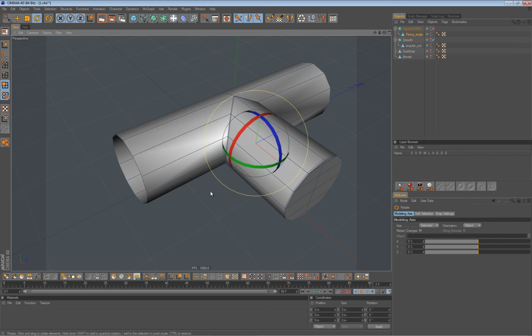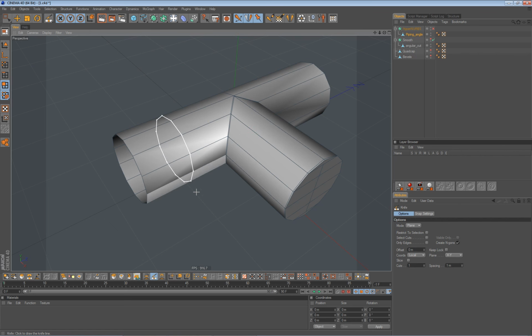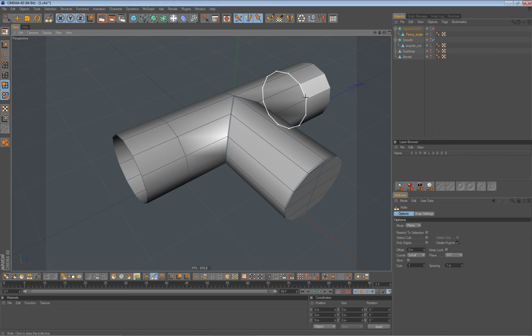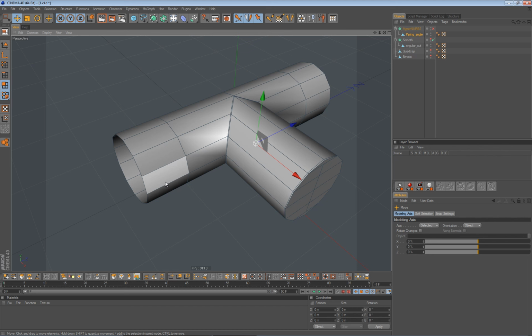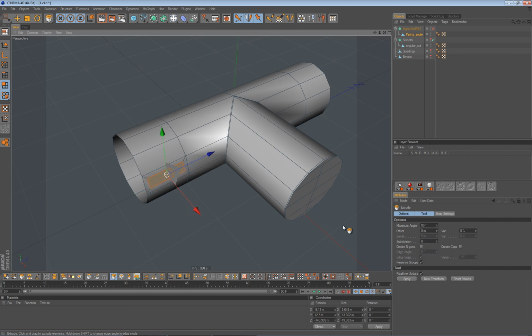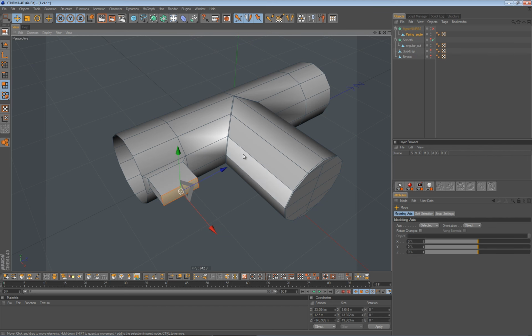Let's just do that. Let me select my knife tool, and it's in plane mode, because if I select loop mode, then this loop will be distorted because of this break in geometry. So I want nice clean loops. I will select plane for this demonstration. So let's say we have some sort of a feature modeled here. Really doesn't matter, a simple something thingy. Okay, something like this.